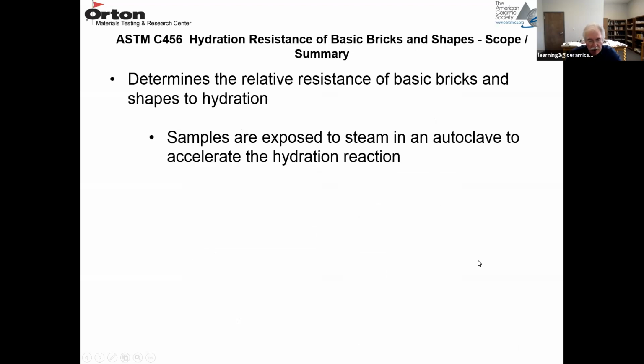And there's only one ASTM test in this section, and that's the hydration resistance. And I mentioned that when lime's present, the material can hydrate rather quickly, and even MgO can hydrate at a much slower rate. So this hydration resistance test determines the relative resistance of basic bricks to hydration, and it's an accelerated test. So the samples are exposed to steam under pressure in an autoclave to accelerate the hydration.